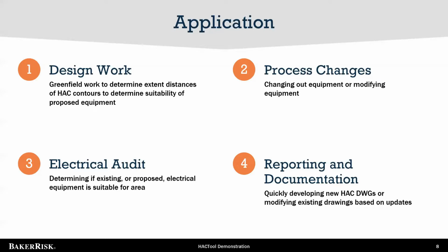It's also, its usability and feasibility is good for process changes. So maybe you're making a change to a unit and you want to know how this quickly affects the classified area boundaries, such that you need to know if you need to order different equipment for your process change, or if the equipment that you have coming in a few weeks or a few months is rated for the area that it's in. And so with just a few clicks of the button, changing out some of the inputs, you can see how process changes affect your classified area boundaries, and also in regards to adding new electrical equipment in the area.